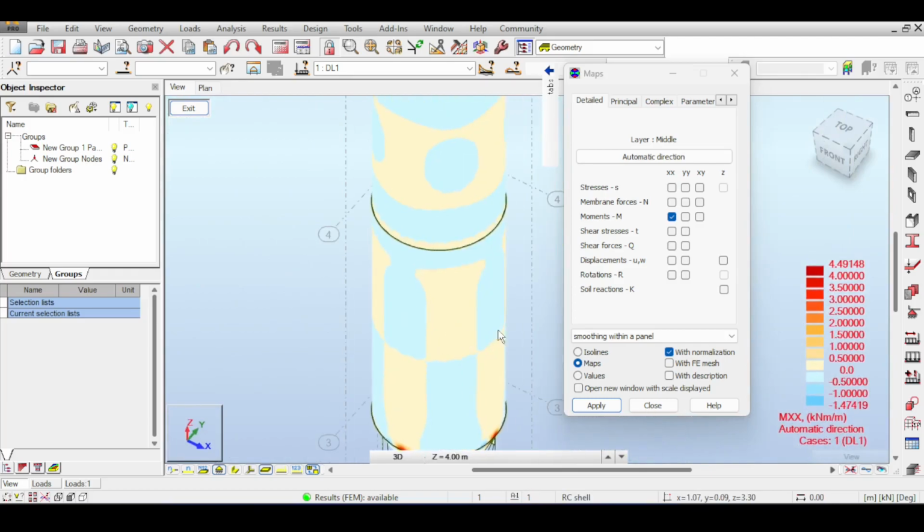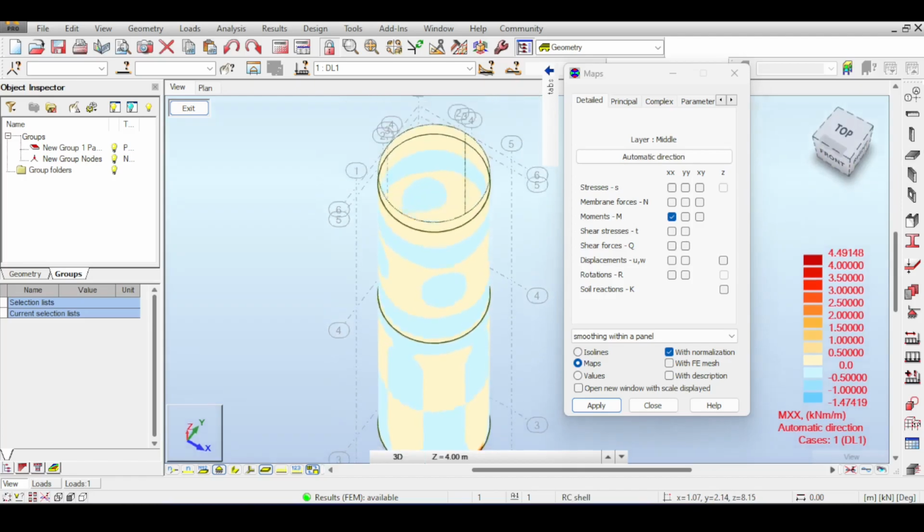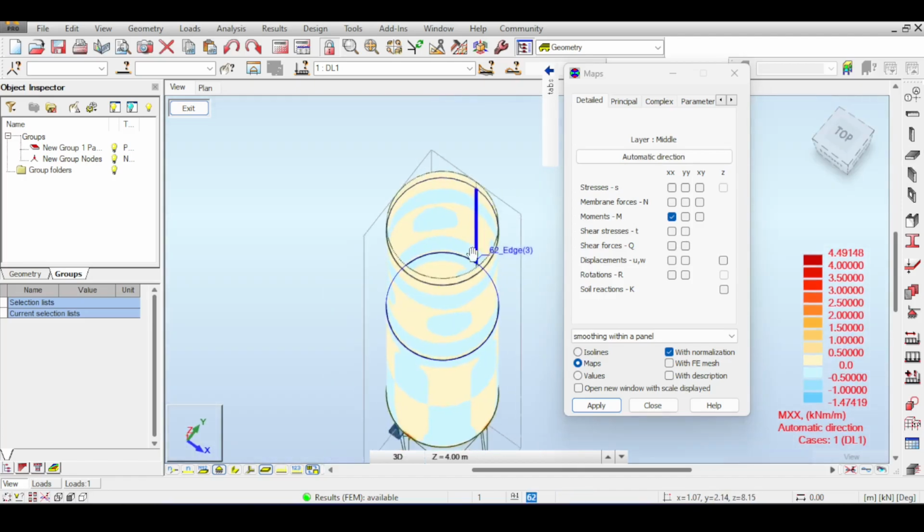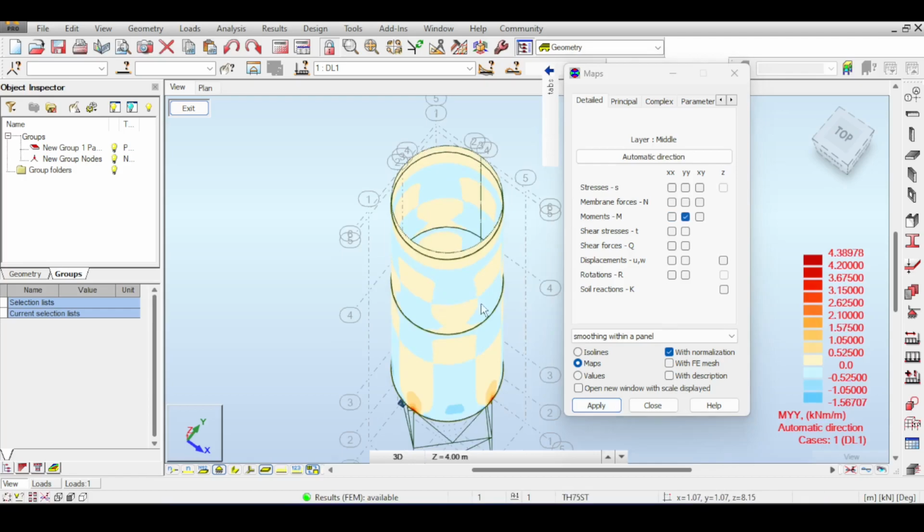But generally speaking, if you want to ignore the stress concentrations for now, the general design here is to design according to those moments. So you take the moments here in X. By the way, X is horizontal. And you take the moments here in Y, which will be the significant moments, as you will see, which have higher values, and design your member based on those moments.